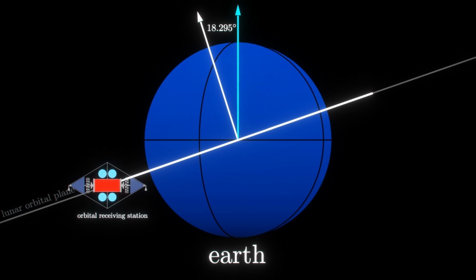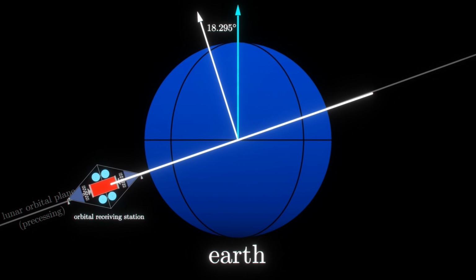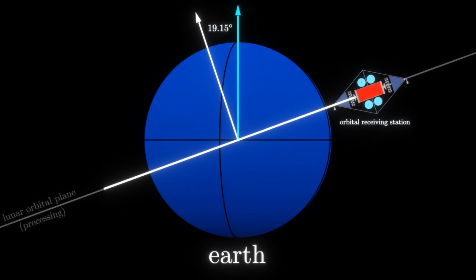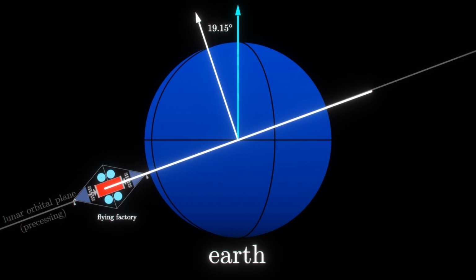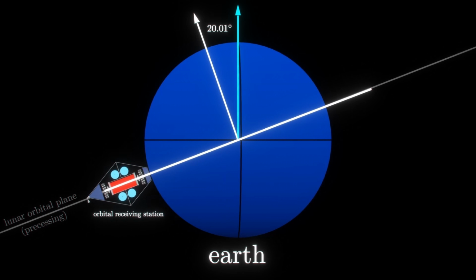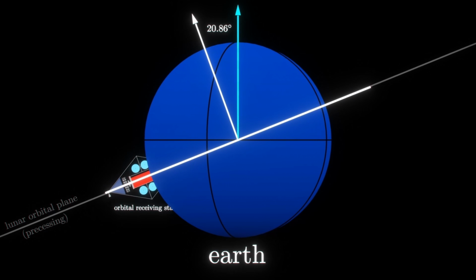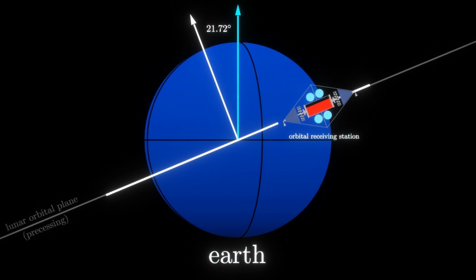Suppose the correction happens daily. Each day, as the station crosses the equator, a thruster performs a small normal burn. The required inclination change is only about 0.003 of a degree per day. At 1,200 kilometer altitude, where orbital speed is roughly 7.25 kilometers a second, that is about 0.38 meters a second of delta V required per day.